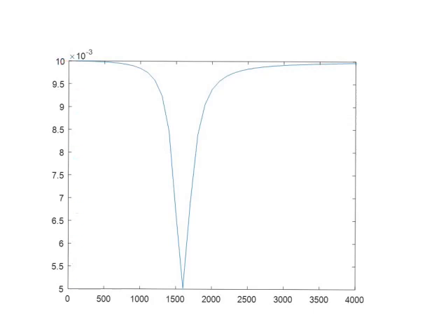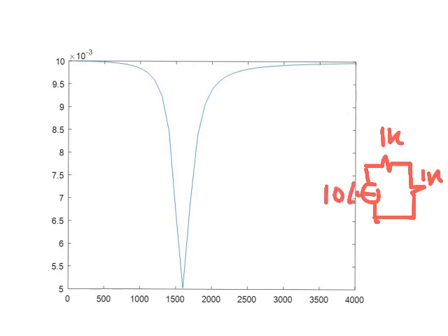Well, let's see. You have a resistance of RS effectively in series with RL at resonance. This is 1K, this is 1K. And your source is sinusoidal, 10 angle 0. So if you divide 10 angle 0 by 2 kilo ohm, the current going through will be 5 milliamps, and this is why at this specific frequency you get 5 milliamps.